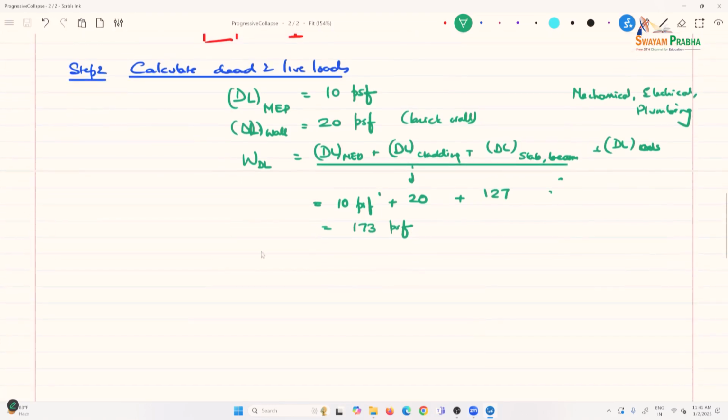The live load itself, typical buildings live load, especially classrooms like this, for us would be 50 pounds per square foot, and partitions. So, this is live load plus partition live loads. In our case, it would be 50 plus 20 or 70 PSF.